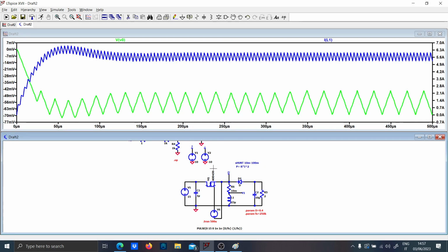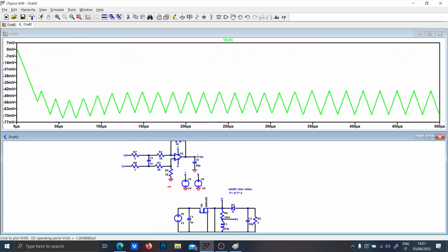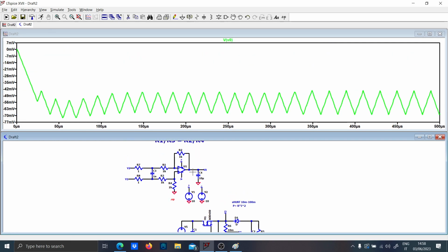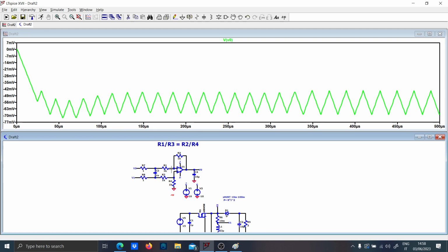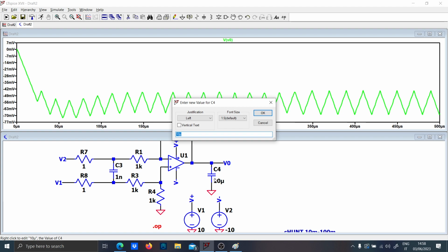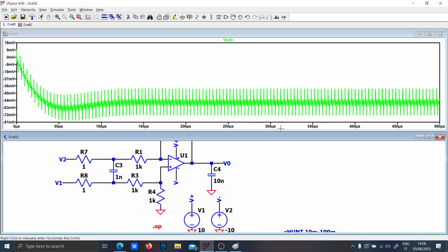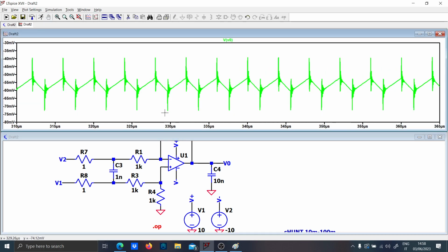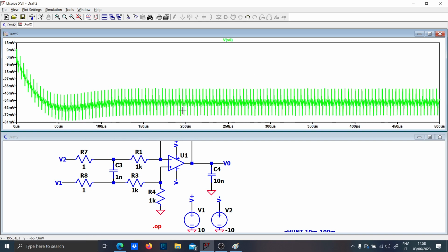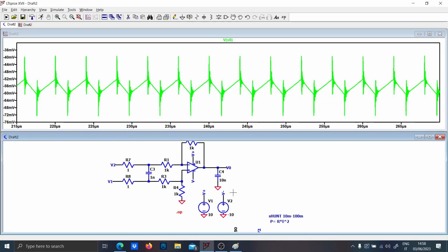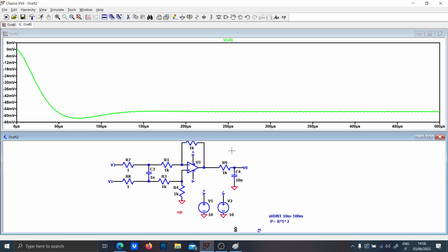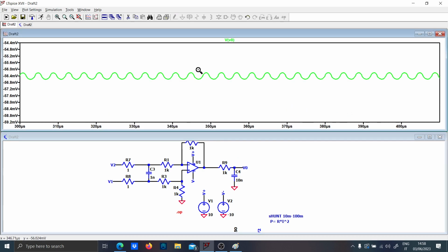So there is some filtering because the op-amp is not so fast. But by the way, this is how for instance you should design your measurement stage. So you can even put, yeah, this is the resonance elements. You will probably see something like this. So just add another low pass filter. 1 kilo ohm, 10 nano, and you should be good.